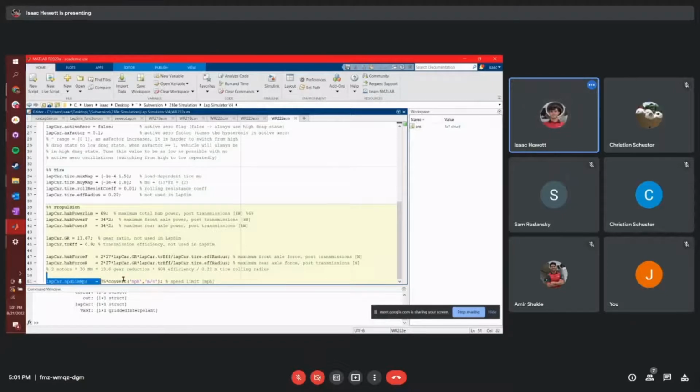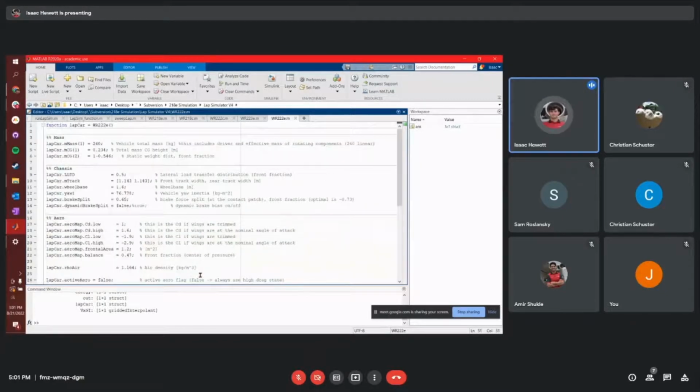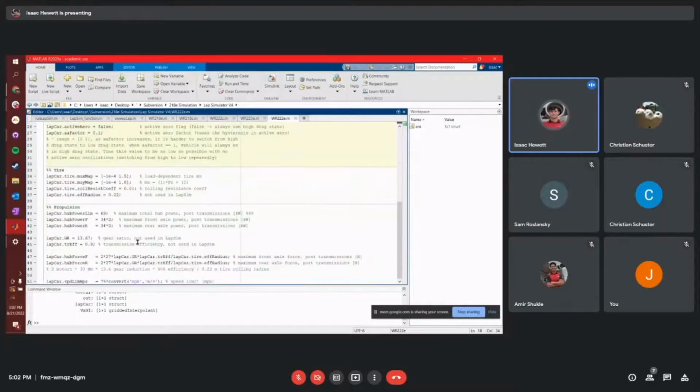And then top speed. So relatively basic stuff. And I think it's helpful to see what we aren't evaluating, right? We're not evaluating things like lookup tables for the powertrain or suspension dynamics, but those are things that could be implemented, or better aero mapping, right? You could have all of these as functions of vehicle speed. If you have the aero map created where you can look up your CL and CD with respect to ride height and vehicle speed, so there's a lot of improvements that could be made, but it's generally a really helpful tool.